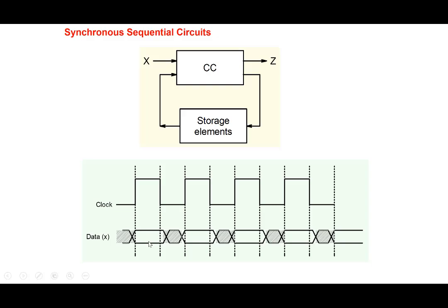While in this case, all data are stable here. So if you feed in the data, let's say one data X comes into an AND gate here, another data Y comes into the AND gate here, well, the output of the AND gate would be stable here. On the other hand, if you look at the output of an AND gate here, X may be changing and Y may be changing, and they may be changing with different delays, and therefore the output of the AND gate is unpredictable. It may change once, twice, or 3 times, depending on how the data is changing here. So the idea is that when you have a complicated circuit, the use of a clock makes sure that there is a time period available where all data are stable, and they have their proper values.